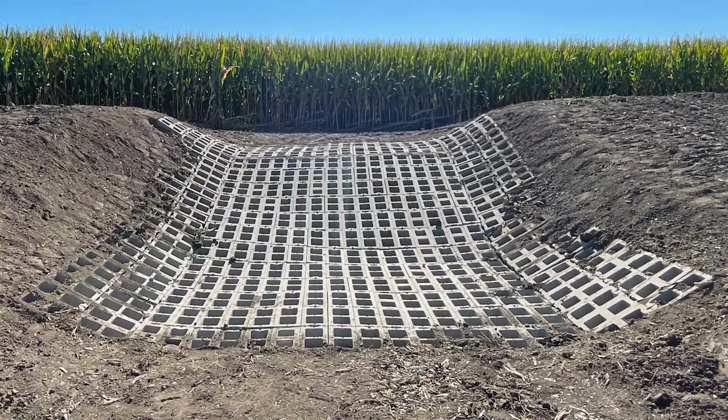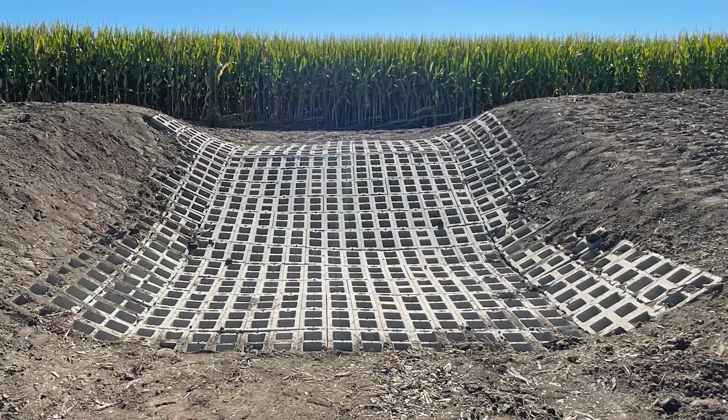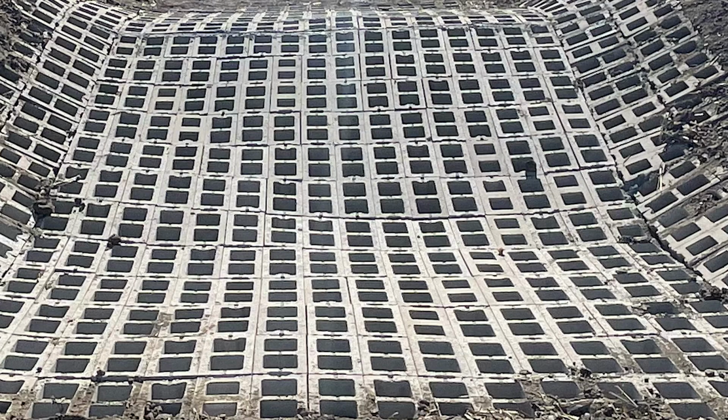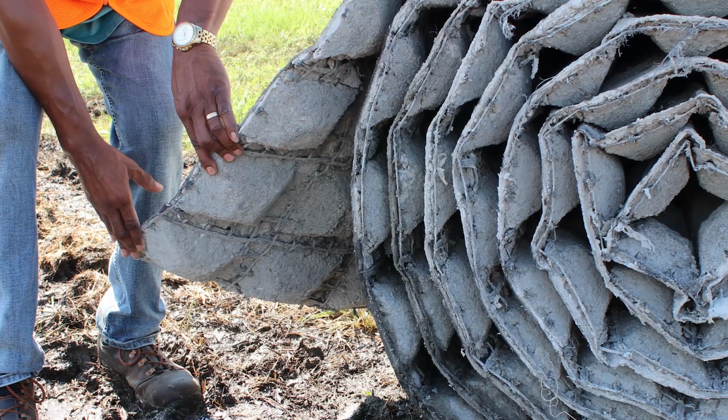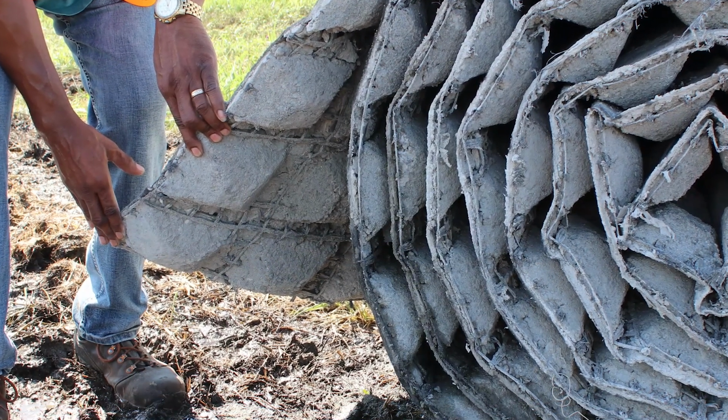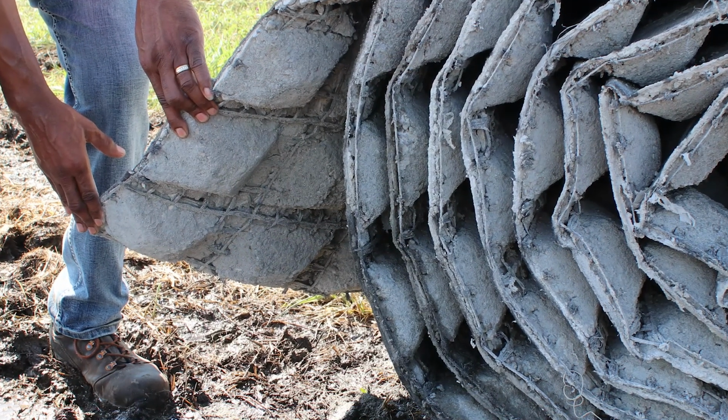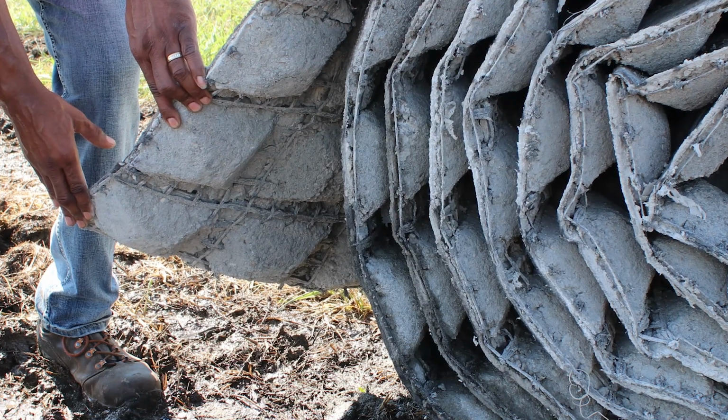Chute structures can be constructed using a variety of materials including rock, cinder block, articulated block, and tied concrete block mats. All of these materials provide protection from high water velocities to eliminate erosion, and all of them have their advantages and disadvantages. Some of the factors taken into consideration when choosing the best method to address a resource concern are effectiveness, overall cost, material availability, labor and equipment requirements, and aesthetic impacts.